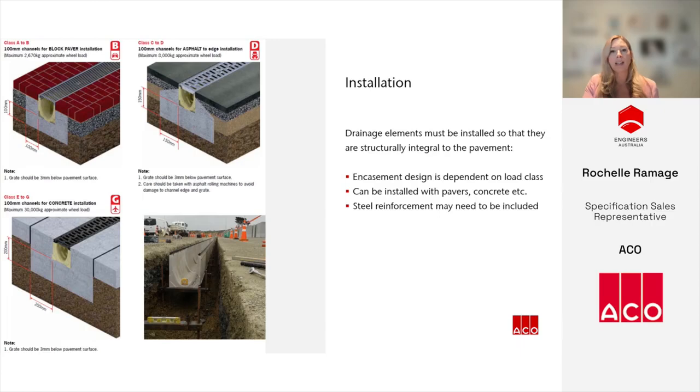Drainage channels need to be encased in cement concrete to ensure they are structurally part of the pavement. The encasement needs to be designed for the project and needs to take into effect construction and design loads, ground conditions, and pavement types. Also, steel reinforcement may be required at times.